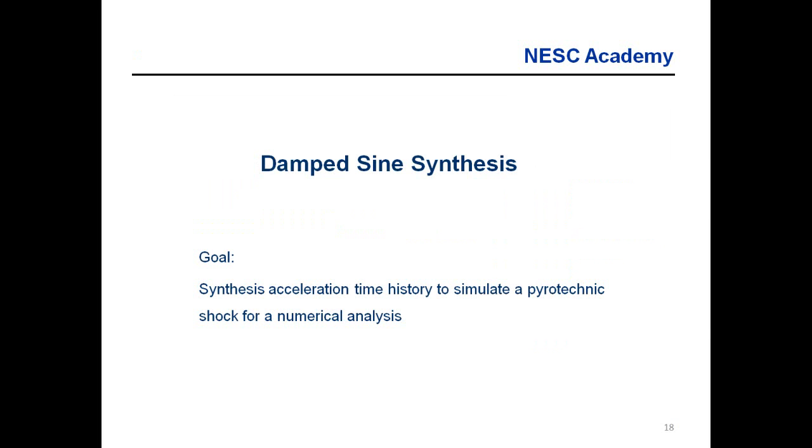Our goal in this case is to synthesize an acceleration time history to simulate a pyrotechnic shock for numerical analysis. Now, that word "simulate" there I probably should have put in quotation marks. What typically happens is we'll measure field data, maybe from a stage separation test or flight accelerometer data, and we'll calculate an SRS from the acceleration time history, or maybe we'll take several and make an overall envelope.